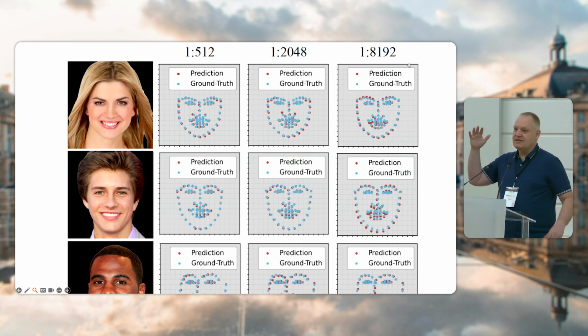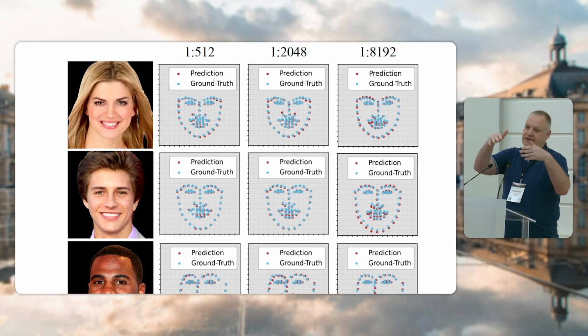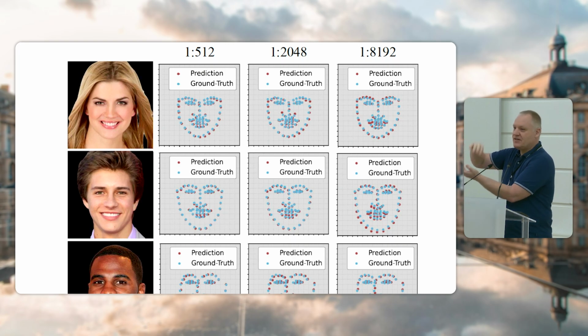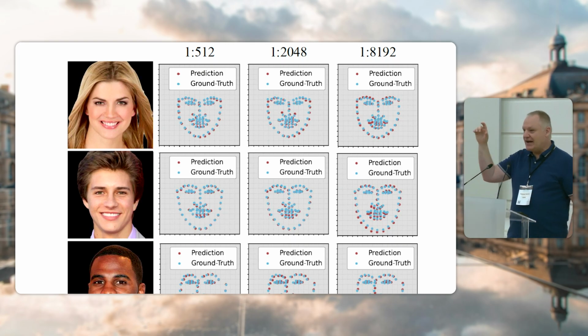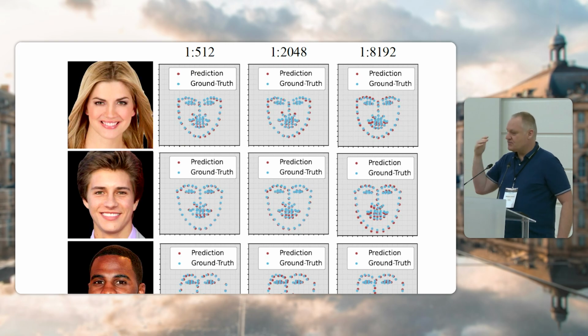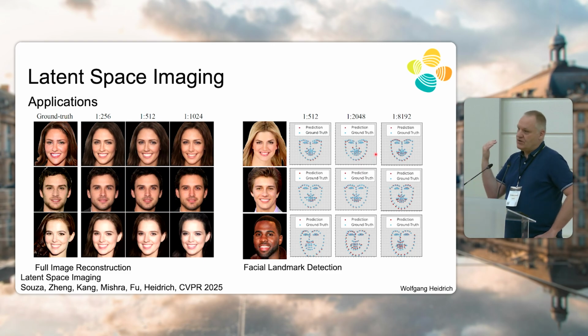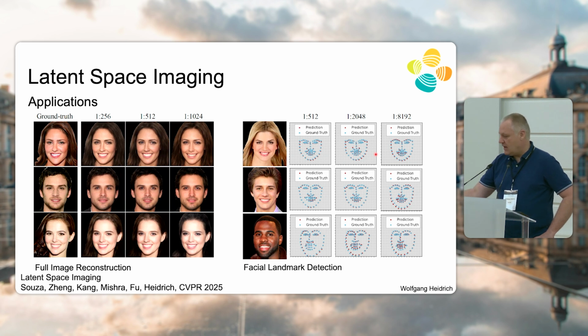So we're doing optical projection through an optical matrix from image space to an 8 vector, then translating that with a really lightweight neural network into the latent space for the generative model, and then analyzing that short vector again with a very lightweight neural network. So you can see that the sensing cost is very low. We can potentially do that at very high speed. You can do the processing with really low latency because the data volume is just tiny.